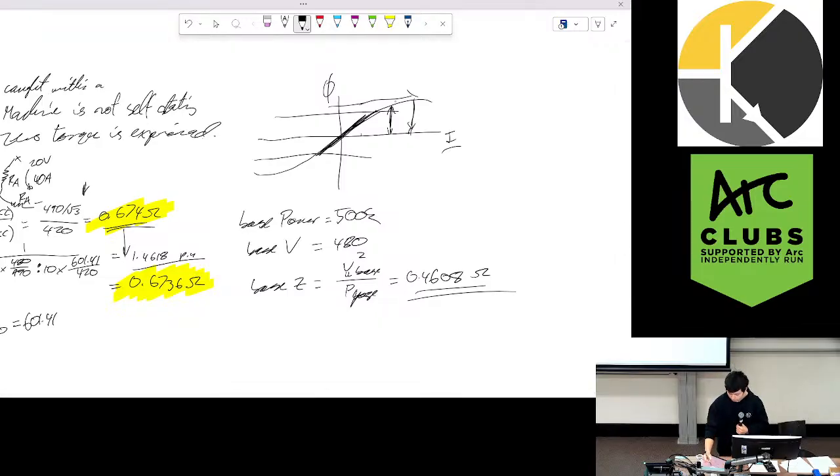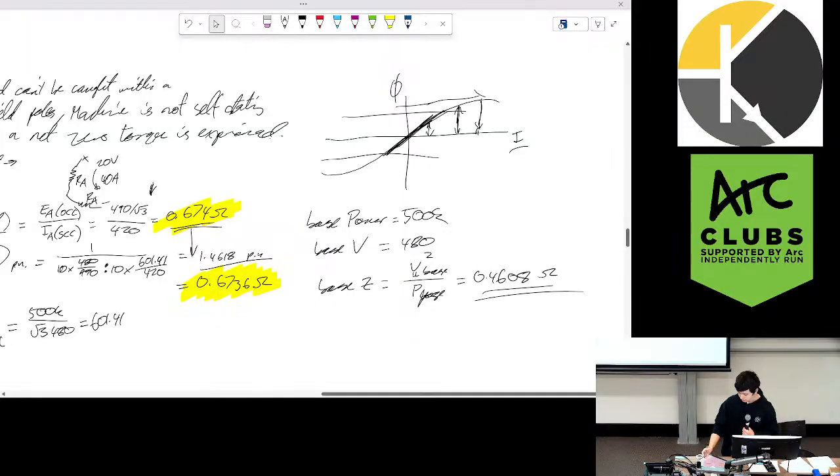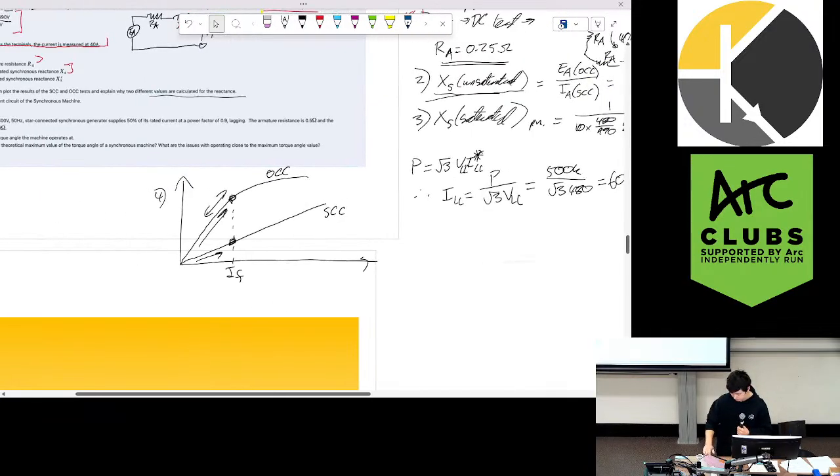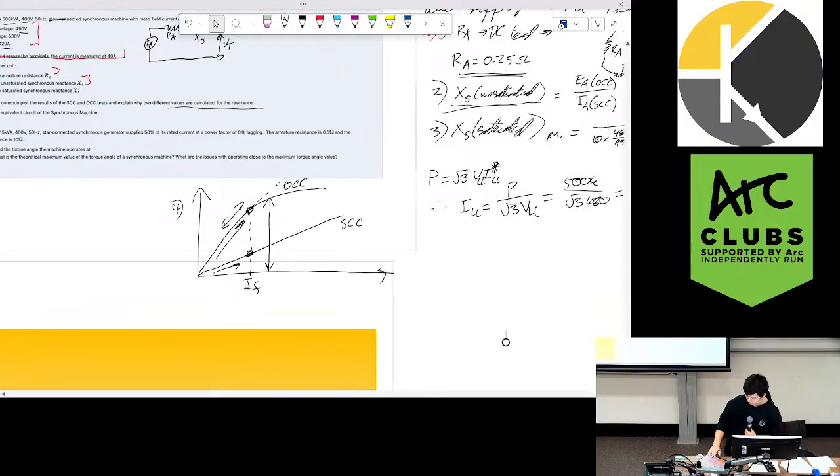However, for some of the tests at the rated current, we might be within the linear region. So we're checking out different regions of our characteristics, looking further beyond, maybe to over here, where we see non-linearity in the system, where we experience some saturation.